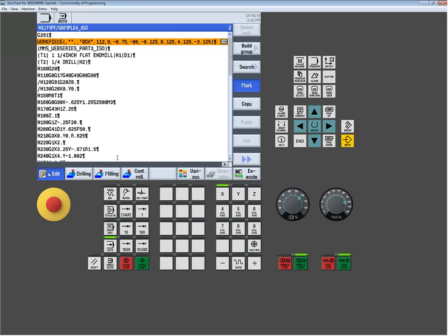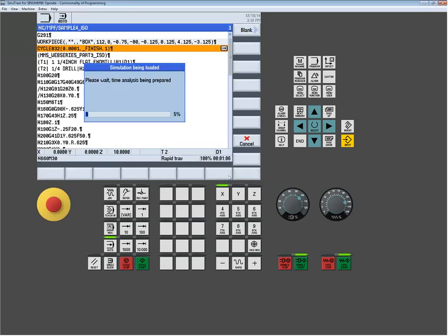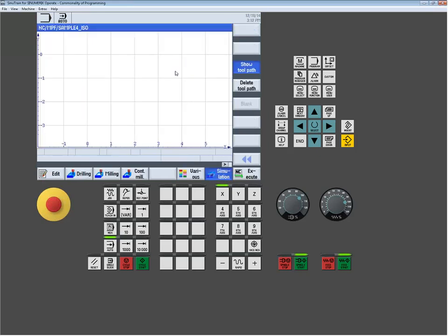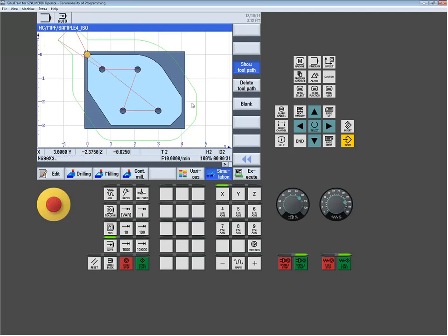So things like, I want to run high speed. So I want to insert a high-speed function into it. Before, that always had to be initiated outside of it. So you can start to intermix. I would be careful, certainly if you're getting to a lot of instructions. So like, maybe I want to add the center drill function like we did before. Well, if you want to do it in the Siemens code, I would switch to our code and then switch back.